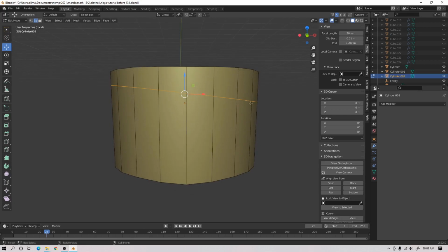All right. So you want to cut diagonal lines like going across, right? So we press K, then Z, we left click and then drag. Then we left click to lock this in, then press enter. We repeat this: K, then Z, left click and drag, left click, press enter, and once more, K, Z, left click and drag, left click, and press enter.